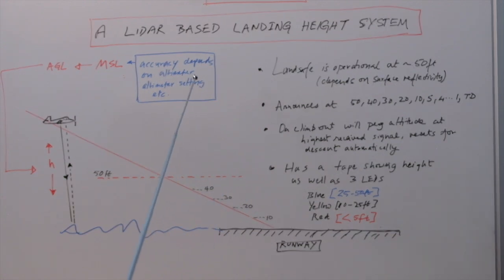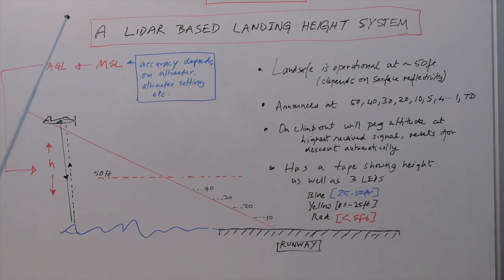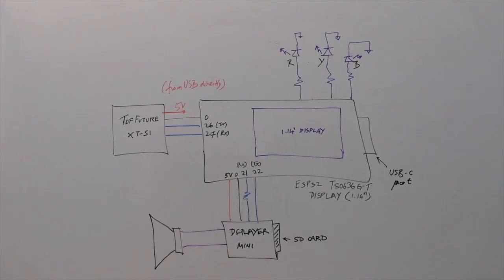They have different side pictures which confuses pilots, and they tend to flare early or flare late. So you want to avoid those kinds of things which can damage the aircraft on landing. This landing height system will help you realize what your real height is above the ground.